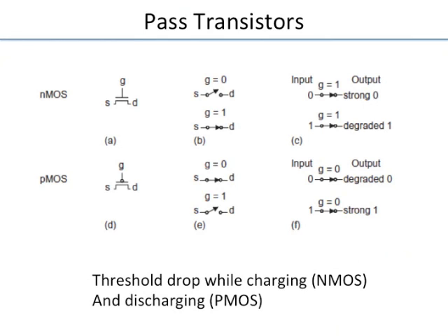If you think of a CMOS gate and in the pull down stack, in some sense we are passing a 0, we are passing the ground to the output. So there is no issue. This applies even for stacks of NMOSes. We are showing this for a single NMOS, but if you take an arbitrary network of NMOS gates, series, parallel, all kinds of combination, you'll have the same problem. That is, 1 will not be passed very properly from the left to the right, 0 will be passed.